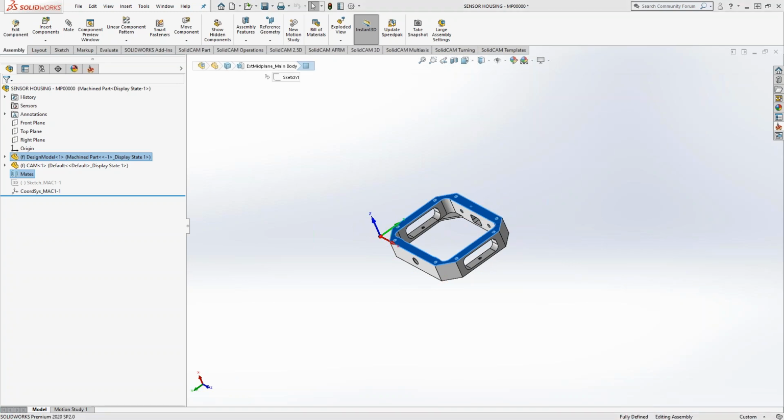That's because inside SolidWorks assemblies, either you have a fixed solid that everything gets referenced to, or it's floating and you have to give it some mates to lock it in place.